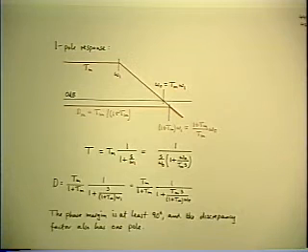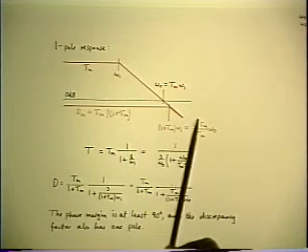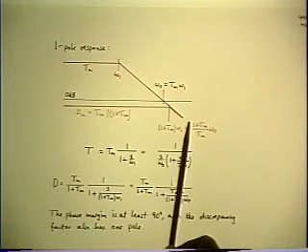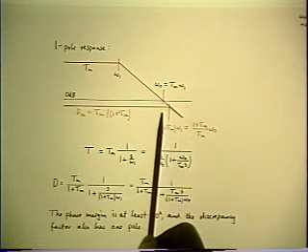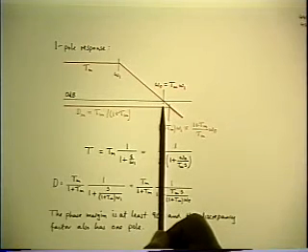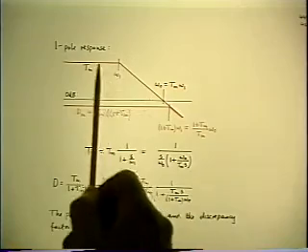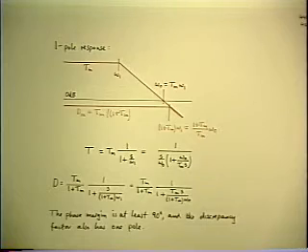Now let's remember, never put more in the problem than is necessary to get the answer you want. It's going to clutter it up, make it more difficult, and obscure the results. Let's get rid of some unnecessary parts of this problem before we make it more complicated again. We're concerned only with the shape of D, and the only important part of that is near the crossover frequency of the loop gain, because as long as the loop gain is large at lower frequencies, the shape of D is going to be close to 0 dB, which is where we want it to be.